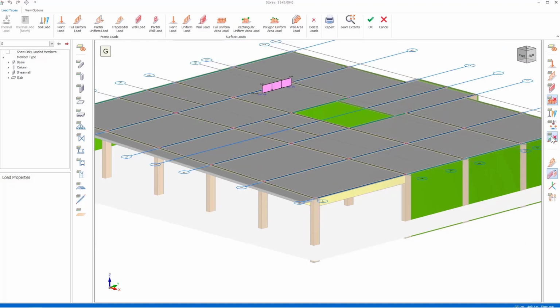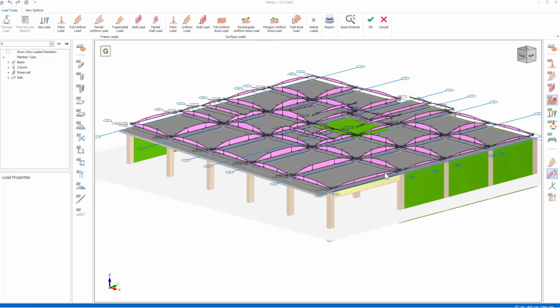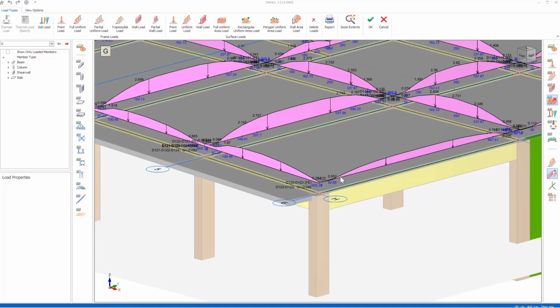ProtoStructure considers the self-weight of the beams as uniformly distributed loads between column faces. Loads decomposed from slabs to beams are defined as distributed loads and are displayed in a staggered manner with spaces between them. Instead of seeing the beam loads separately, you may want to see them as a combined single profile.